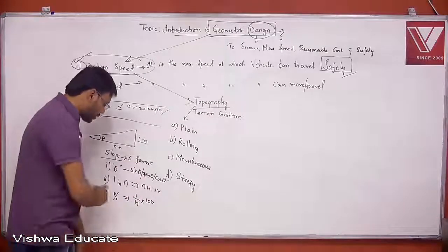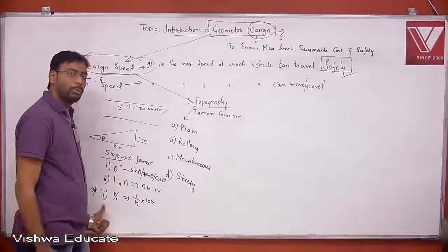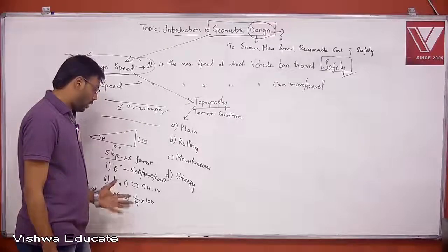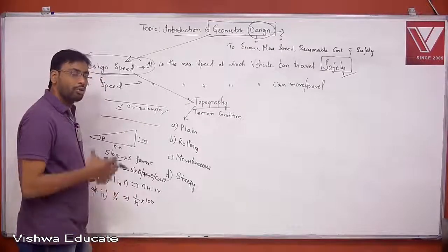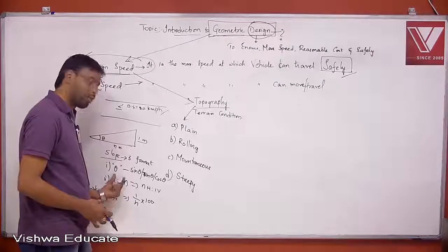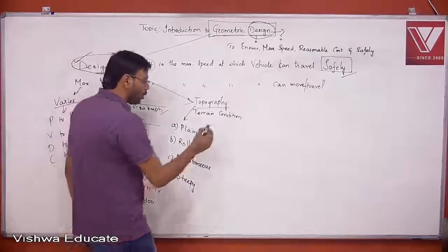And in transportation engineering, mostly I will be using slope in percentage format. So you need to know how to convert 1 in n into percentage, and from percentage to 1 in n format, which we'll be doing in some of the problems.